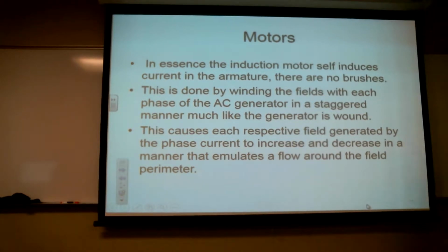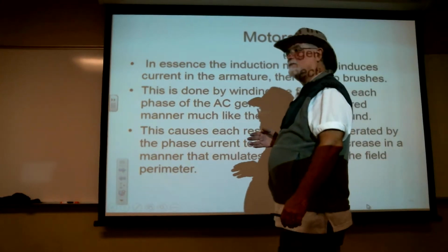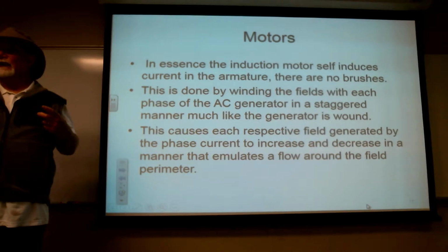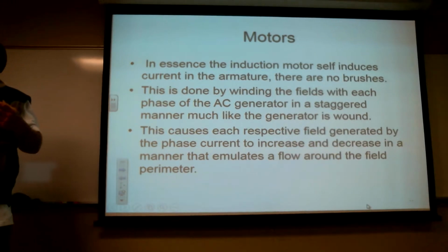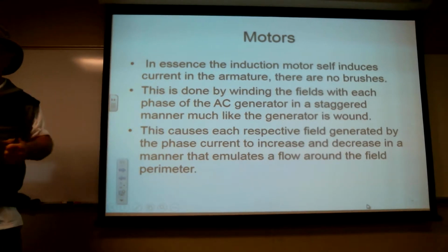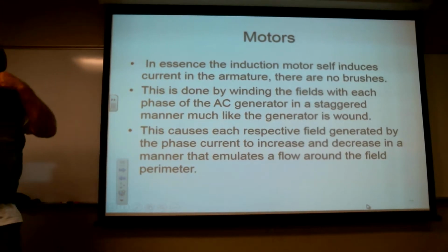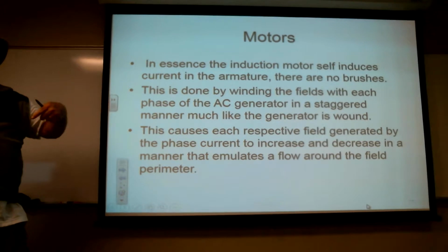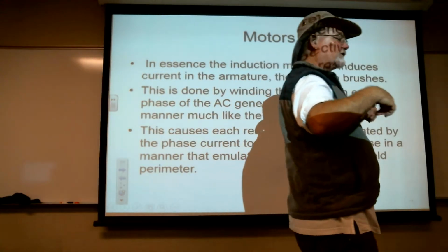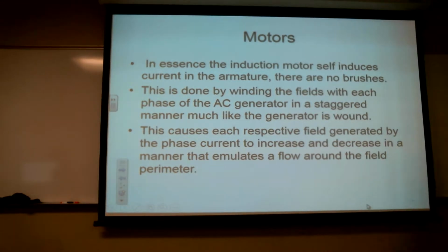As they start producing current flow in the iron bars, in this little spinny thing, that current's going to create its own magnetism. And that magnetism will start reacting to the magnetism that I've got spinning things around. So that set of magnetic bars hooked on a spindle will start trying to follow the magnet. Now it has to have some slippage, but it'll start trying to follow.